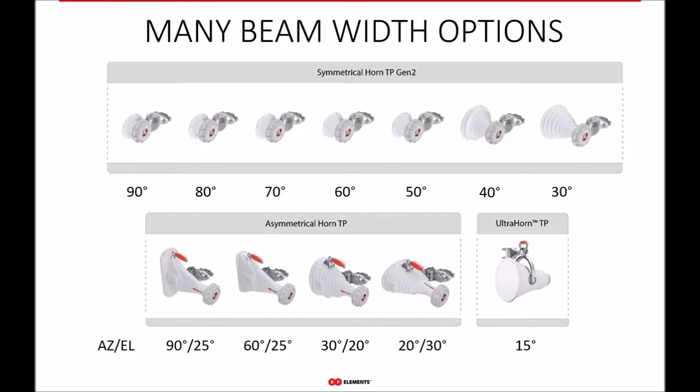And in the same row, you can also see an example of a 24 dBi gain horn. We call it the ultra horn, which is good for point-to-point applications or narrow sector applications. And this is, for example, a point where some WISPs are questioning: so what is this antenna good for? This ultra horn, is it a point-to-point antenna or is it a sector? Well, the answer is it's up to you. Whatever works for you. It can be a narrow sector, it can be a point-to-point antenna.